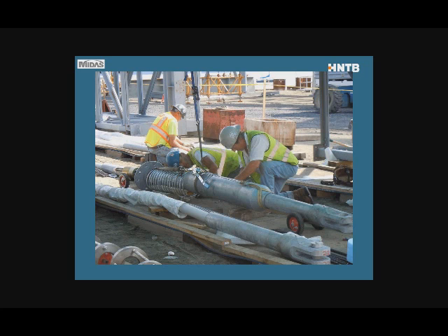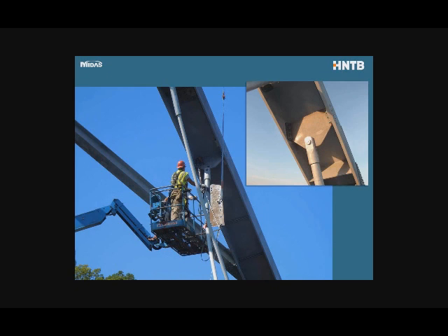And here's the assembled cable, actually 2 side by side. The one that's currently being picked up, that's a very short one near the ends of the arch rib. So you can see we have the pin, we have the anti-vandalism where that yellow sling is just long around, and then we have the rebar and the lower flange plate where it's connected to the tie girder. So this is a very tiny one. The one in the foreground is more typical, where you just see the upper anchorage.